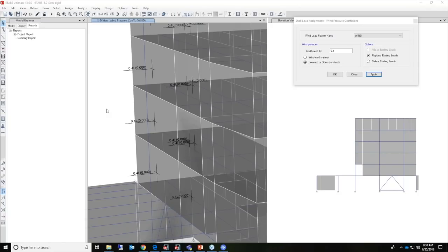All right. So when you modify exposure height, what mean roof height is used to base the wind loads off of? The top of the exposure height should really always be the roof. If you use something lower, that actually means that you're going to apply some additional loads yourself to the roof.